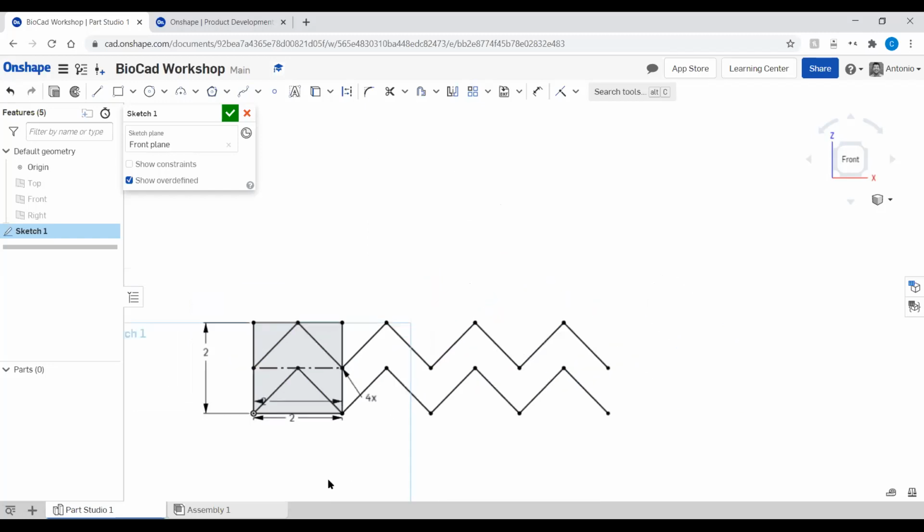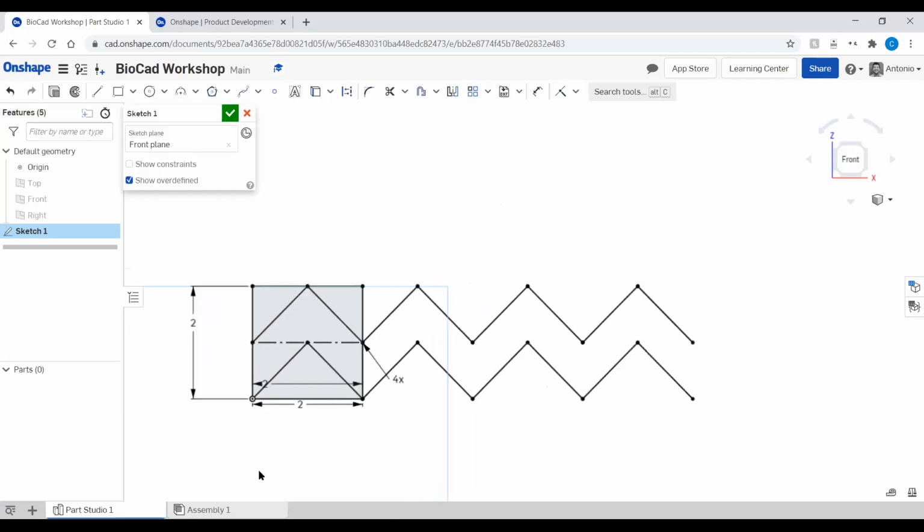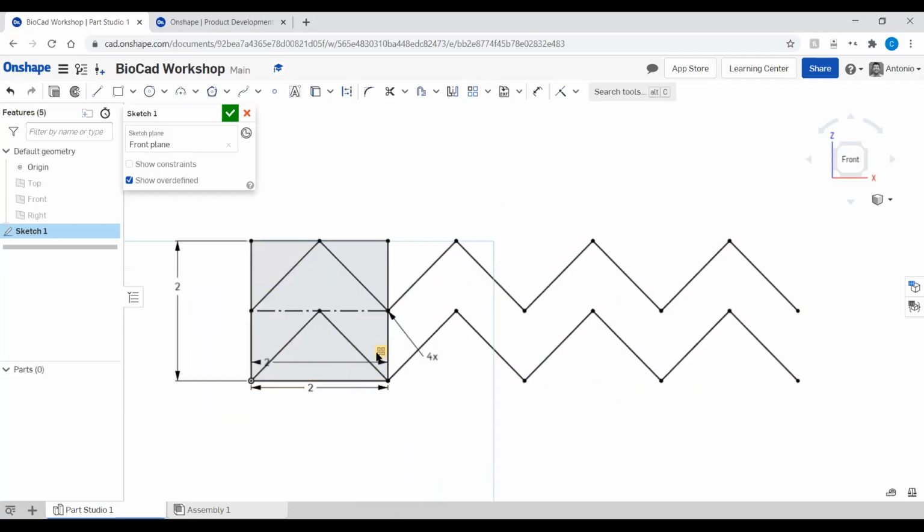So from here, this is about half, like 45% of one unit cell. What we're going to do now is move on to step 2, which is create our connector, which Anusha talks about. We're only going to create half of our connector, because we're going to leverage the repetitive and mirroring functions of OnShape to create the rest of it.